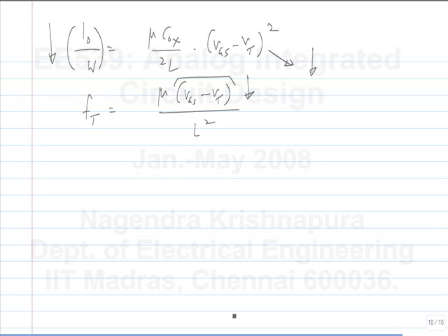Is this clear? So again, the amplifier is very familiar to you. What I wanted to discuss was more of trade-offs of this nature that you will come across, especially when doing an IC design. I mean, this is true even of discrete design, but if you get a discrete MOSFET, you have no way to change its width or length or anything of the sort, right? So in IC, you have freedom to do many things. That is, you can change its aspect ratio or you can change its operating point. So the job as an IC designer is to figure out how each of these things, the bias point as well as the aspect ratio, changes the performance of the amplifier. After that, you will be able to tailor your performance to whatever specifications you are given.